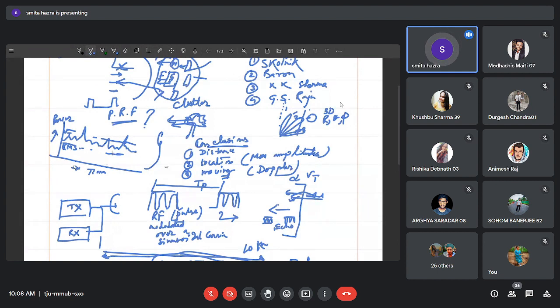But sometimes the component of the echo signal coming from a really appearing object becomes so small that it is totally masked by the noise levels or by the clutter signals. Clutter means the background, all the fixed objects present in the background. So sometimes it may be covered by them. Then it becomes very tough to detect that very weak or faint echo signal which is really coming from a new object or a new intruder.